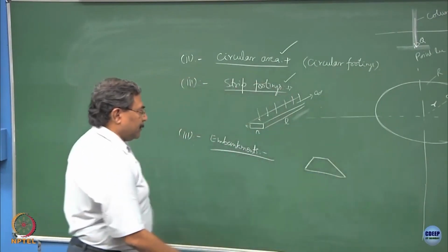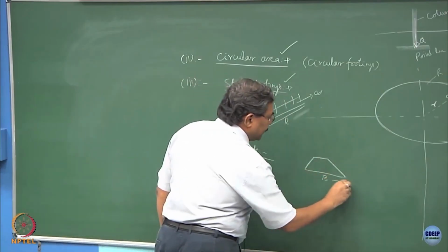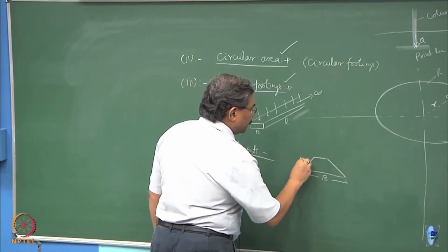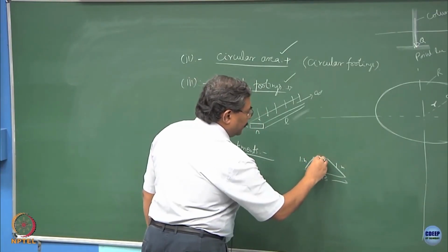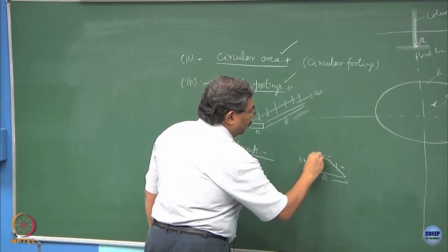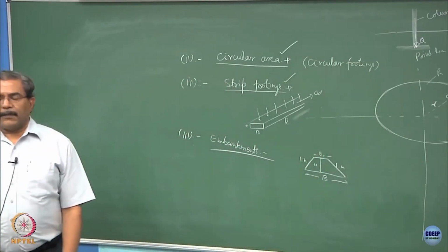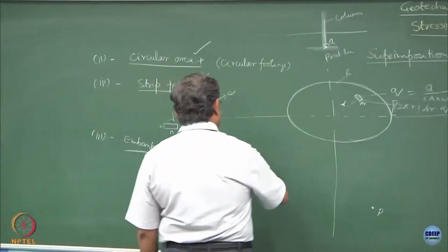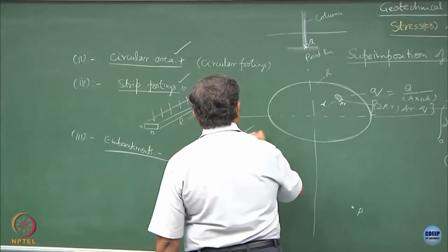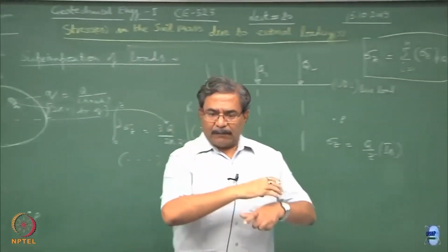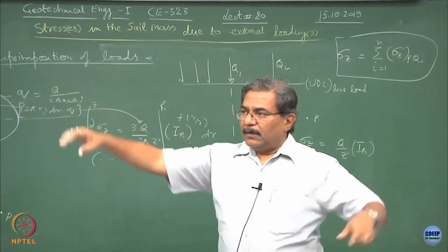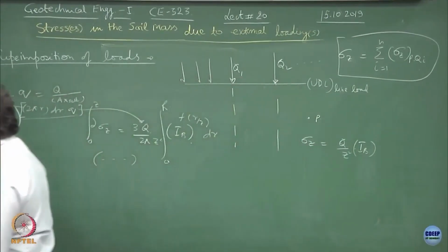So you have a certain specific width at the base, slopes 1:n, 1:m, if you remember. We have to define the height and the top width of the embankment, and this embankment also tends to infinite length, like a railway embankment. Railways pass through kilometers of lengths of these types of embankments. Agreed?